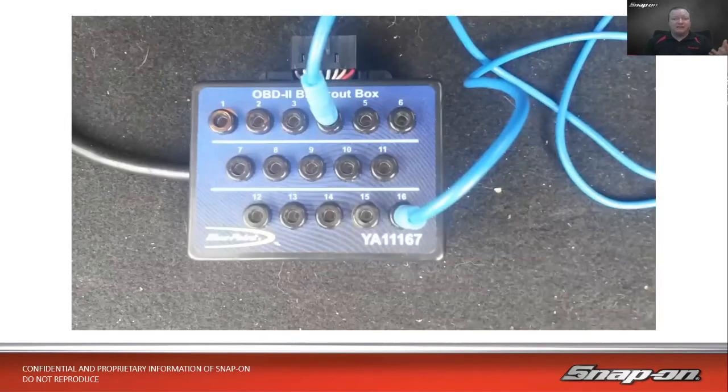Now, how am I going to access that? Well, we don't want to front probe. We don't want to push in to those pins on the DLC, right? Because that could cause a communication issue in and of itself if we make those pins break. Usually it's pretty hard to get behind those pins as well because they put that diagnostic connector somewhere under the dash, which isn't always the easiest thing to get to. So sometimes it's hard to get to the back. So the easiest way to do this, non-intrusively,